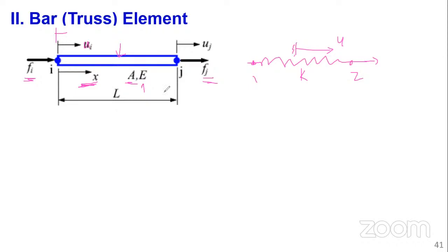So when we come to the beams, you may wonder why instead of talking just of A, we'll be talking of even I when we come to issues of bending. Here our member just carries axial load, tension, compression. So what is of interest to us is the cross-sectional area, because we'll be talking of the stress in the member. No moments, no bending. So we are interested only in the cross-sectional area to be able to either analyze first and then design our truss member.